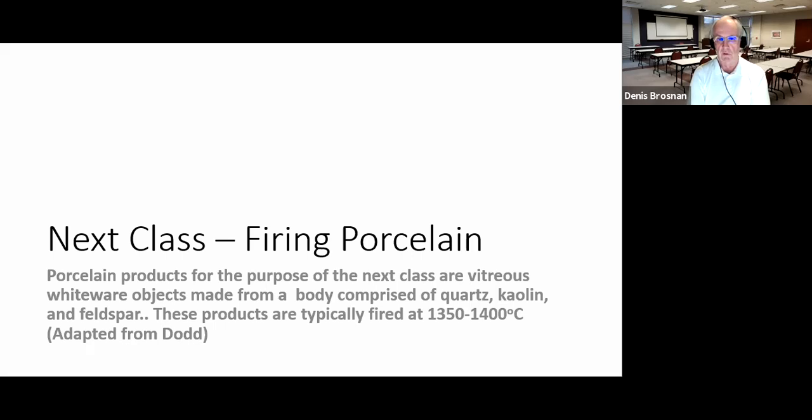We've seen other things that come along for the ride from naturally mined materials like iron sulfide, limestone, gypsum can be present. There's a lot of technology that we haven't talked about. I've always liked the fact that limestone was intentionally added to some bricks, limestone fines, to help in carbon burnout throughout history. When the limestone decomposes, you get CO2, and that decomposes into CO and some oxygen, and that helps in carbon burnout.